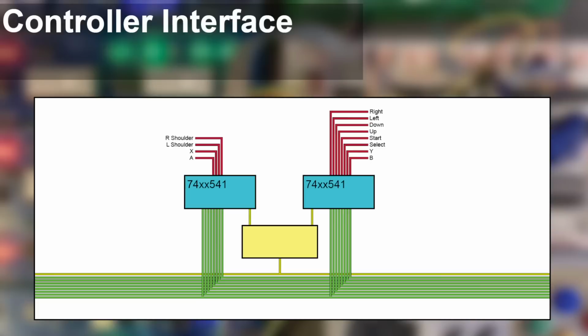Now, in an ideal world, we'd have 2 different assert lines that would allow us to do this, or we could use a flip-flop to alternate between them and have some kind of external mechanic to synchronize the flip-flop so we know which state it's in. When I roughed out the original plan for this whole system, I included the 1 read port for controller. And so what I'd like to do is try and come up with a way of including this extra functionality without bringing any other system resources to bear.